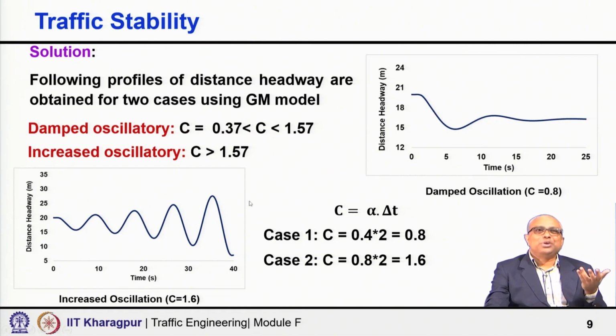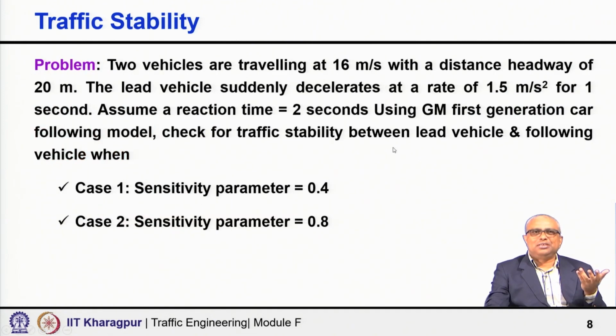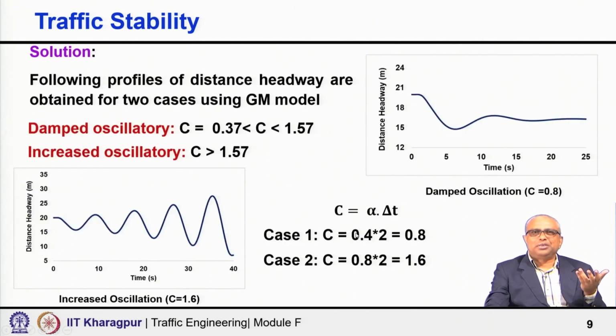You can calculate the distance headway for both cases, and I have just directly plotted the values here. This shows the distance headway against time in case 1 and also in case 2. You can clearly see that this is a case where oscillation happens, but then finally it becomes stable.